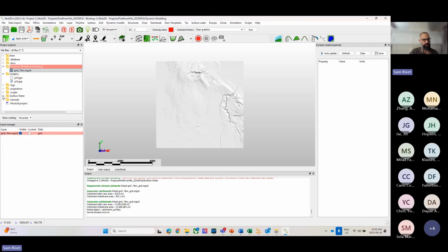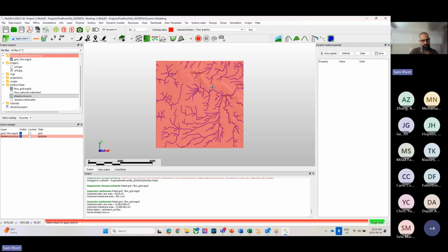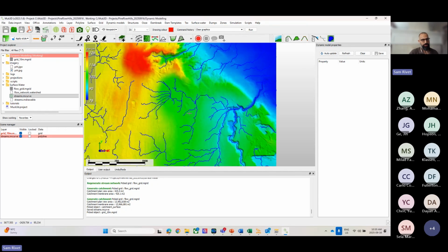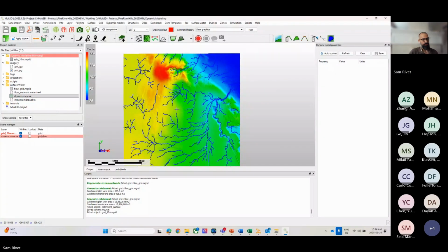All right, for reference, I'm going to open up my streams again. I'm going to apply that elevation style to my overall topographic surface. And I'm going to take a look at maybe creating a ditch, creating a sump, maybe rerouting one of these streams to that sump with my ditch and an excavation or sump network here. Just something quick, but fairly accurate.